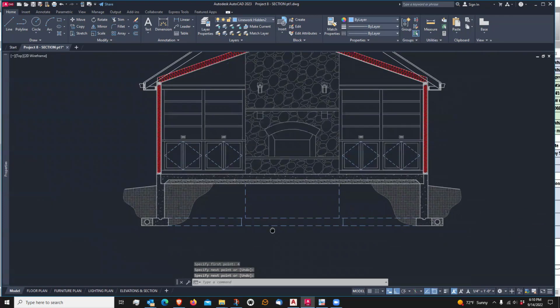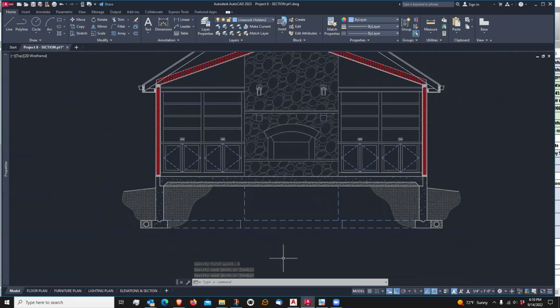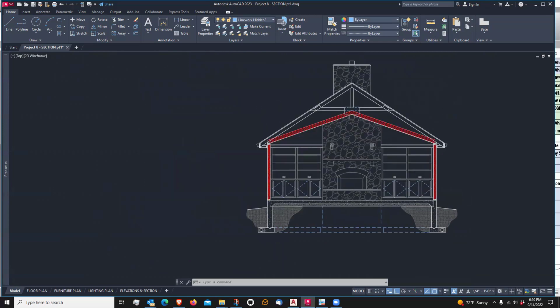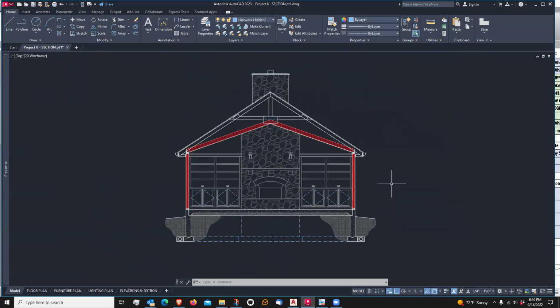So pretty simple, pretty straightforward, but it is an important component of drawing a building section. We want to see that the footing and the foundation walls are continuing around the backside, even though we're seeing it cut through here. We need to tell the contractor that it is continuing. Now, the contractor will actually use, you'll have a structural engineer most probably involved, and your structural engineer, he or she will draw the plan of the footing and the plan of the foundation wall, etc.